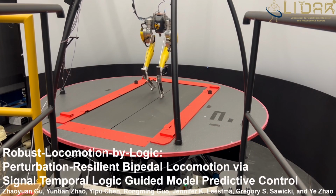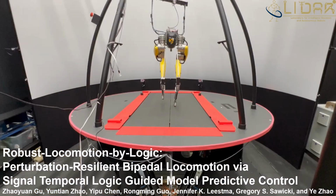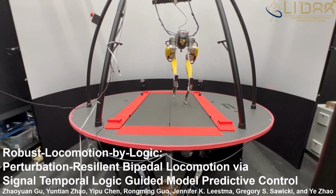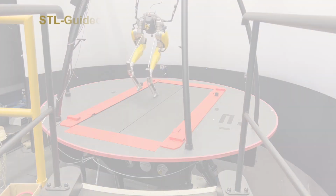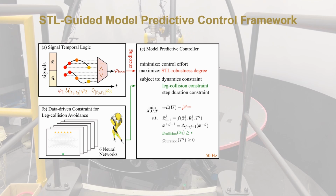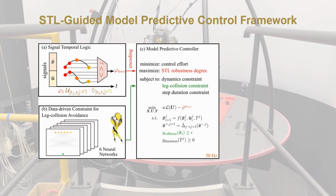We present a robust locomotion by logic framework, where we achieve perturbation-resilient bipedal locomotion via signal-temporal logic-guided model predictive control. In this study, we use formal methods to quantify the locomotion robustness and guarantee the completion of locomotion tasks. Specifically, we encode signal-temporal logic specifications into an optimization-based model predictive controller.